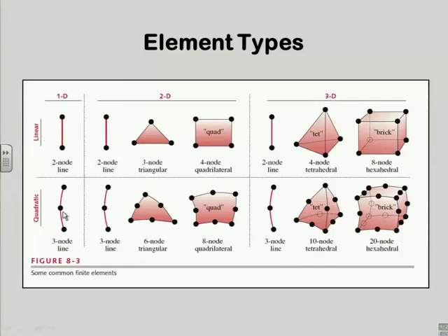What is meant by order is the simplest would be a linear element, and this is the one I was just showing you that I represented as a spring. It's called a line element, okay? All it can do is pass a force in one direction. Now, when would you use that? If I'm analyzing a truss in a bridge, because the assumption is the forces exist only in the truss elements, and they're in one direction, which happens to be the angle of that truss element, right?